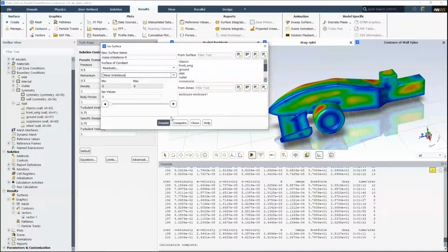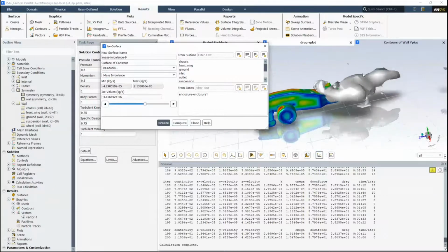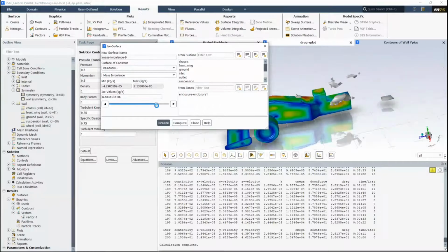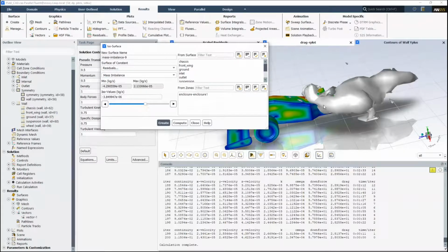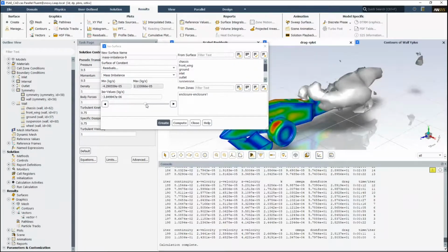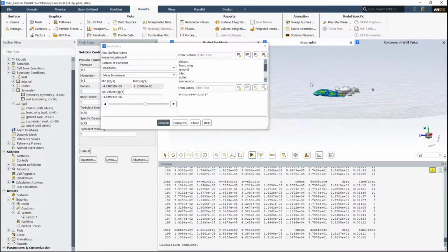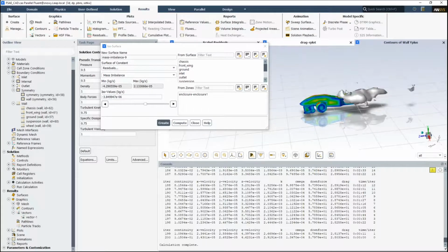So you can see our mass balance residual. We're going to look at some value. Okay, you can kind of narrow it down further and further, but I think up here is a really good value. So everything within this surface has a higher residual than 1e-6. Okay, and so we can see that our problem areas are actually mostly not around here, but around here.